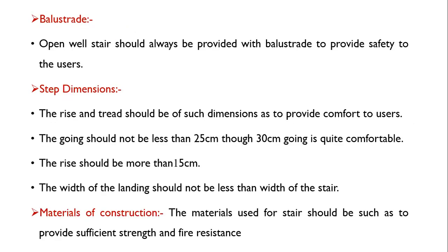Then balustrade. Open well stairs should always be provided with a balustrade to provide safety to the user. Balustrade is the assembly consisting of handrail, balusters, horizontal members and vertical members. So it is called a balustrade, and it provides safety to the user.